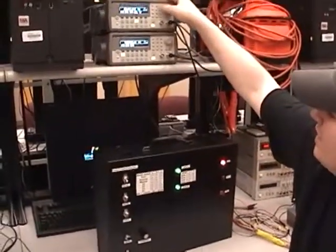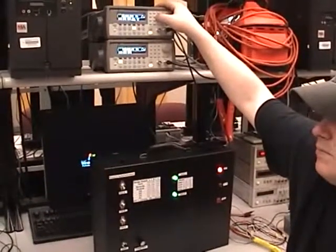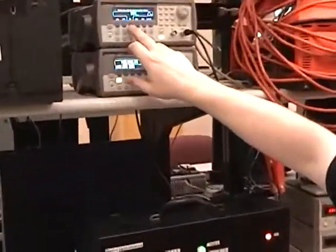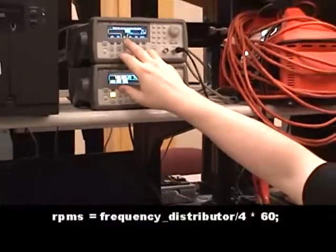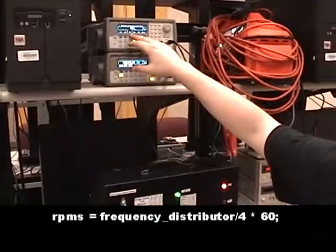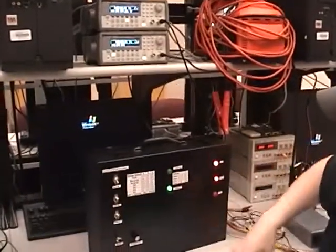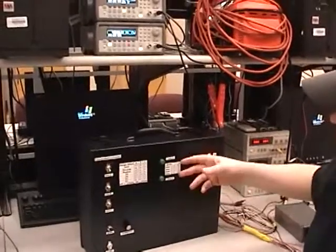So we're going to go ahead and do that now, and I know that we had it set at around 4,800 RPMs. So we'll go a little bit higher than that. I think 500 hertz would be around 4,800 or 4,900 RPMs, because it's going to be your distributor signal divided by 4 times 60 to get to revolutions per minute. So you'll see it went from first to second, and then it went to third,